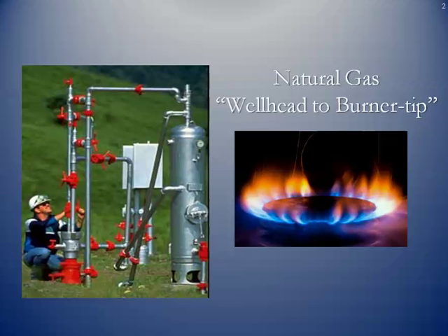That's known as a Christmas tree, the configuration of the various valves. And to the right is what's known as an oil gas separator. First thing that happens when the raw natural gas comes out of the ground is to separate the heavier components, the oily substances, which in essence are what we call condensate.